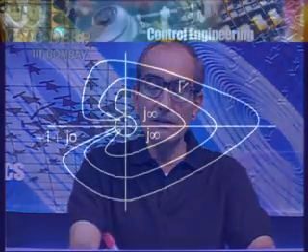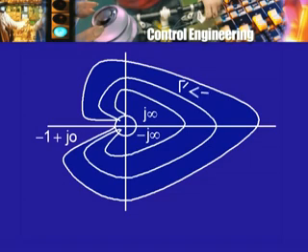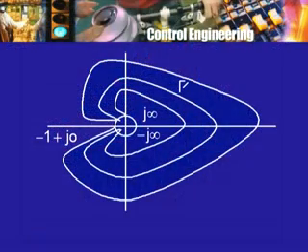Now, therefore, this is the contour gamma prime, which is the image of our original contour gamma. And now we are ready to apply the Nyquist criterion to this plot. Now, remember, we have to consider the encirclements by this plot of the point, of which point? Not the origin, but of the point minus 1 plus j 0. Now, for high frequencies I am very close to the origin, so the point minus 1 plus j 0 might be somewhere here, let us say. Now, it is clear from this figure that this plot, that is gamma prime, does not encircle this point minus 1 plus j 0.